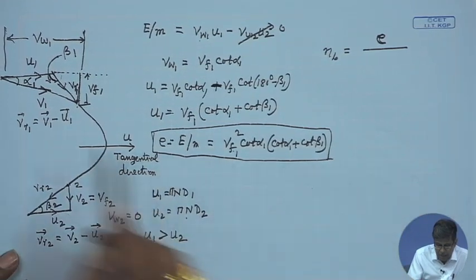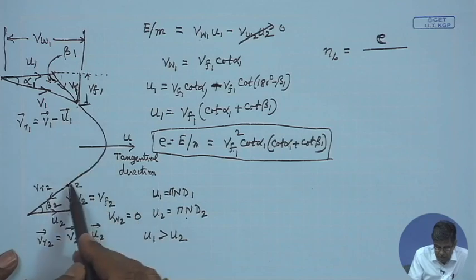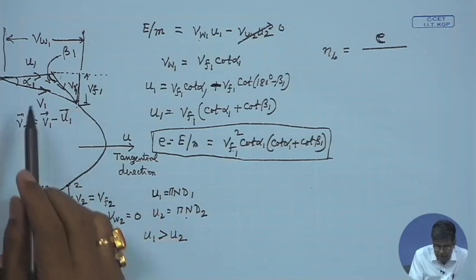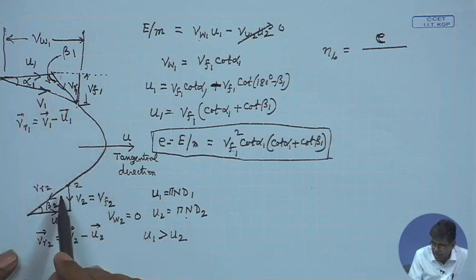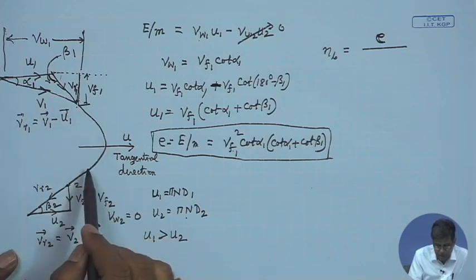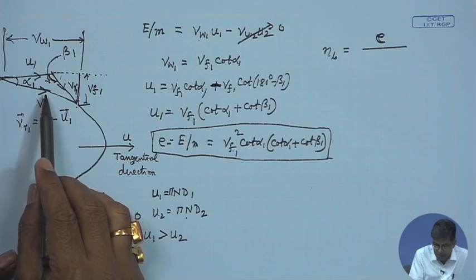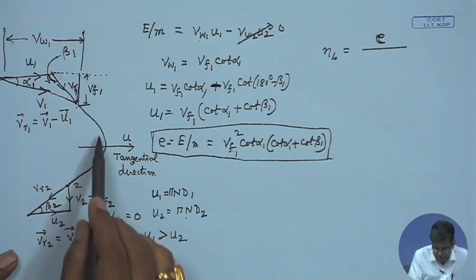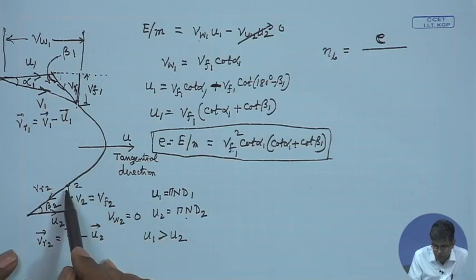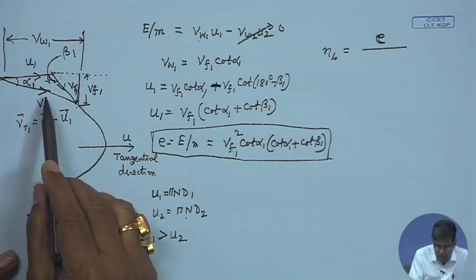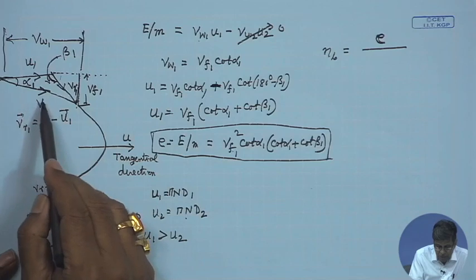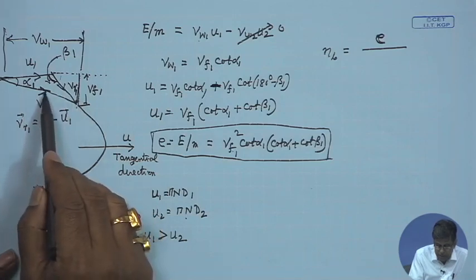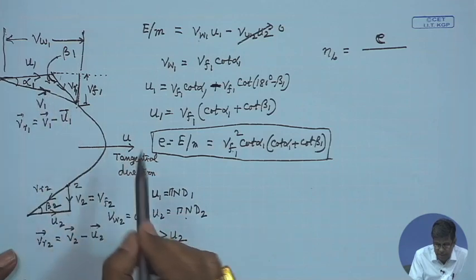Earlier in Pelton wheel, the input energy to the runner or the rotor is the kinetic energy of the fluid, because pressure throughout was the same, that was the atmospheric pressure. But here there is also a pressure energy or the static head which changes in the course of its flow. So, therefore, we cannot find out straight away from that concept that V1 square by 2. So, we have to know the pressure energy or pressure head or static head at the inlet to this runner.